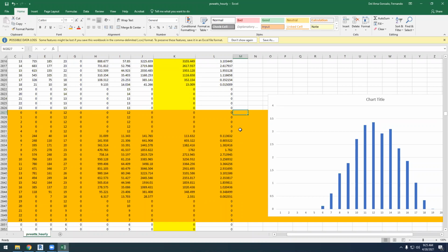If we know the schedule of the building, if the building starts operating at, let's say, 7 a.m., okay, so at 7 a.m., if we know the load of this building, it can be, I don't know, 2.5 kilowatt hours. And then we make it 2.5, but in the afternoon or in the evening, we have 3, and then we have 1, and then we have 0.5, and after that, we have 0.